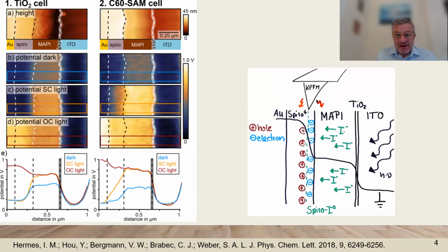It's very interesting, the Kelvin probe force microscopy. It's going to track the local vacuum level and show where the electric potential is constant and the band more or less flat, and where is a drop of the potential and accumulation of space charge.